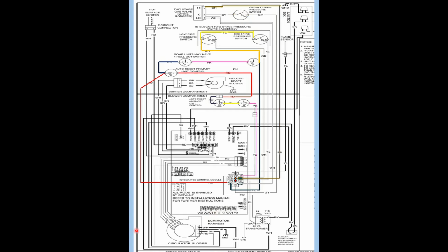Because it's open, you don't have that. And if by some chance that front cover pressure switch was closed, it wouldn't matter because it would trigger an error code. If your front cover pressure switch was closed, it needs to be replaced.